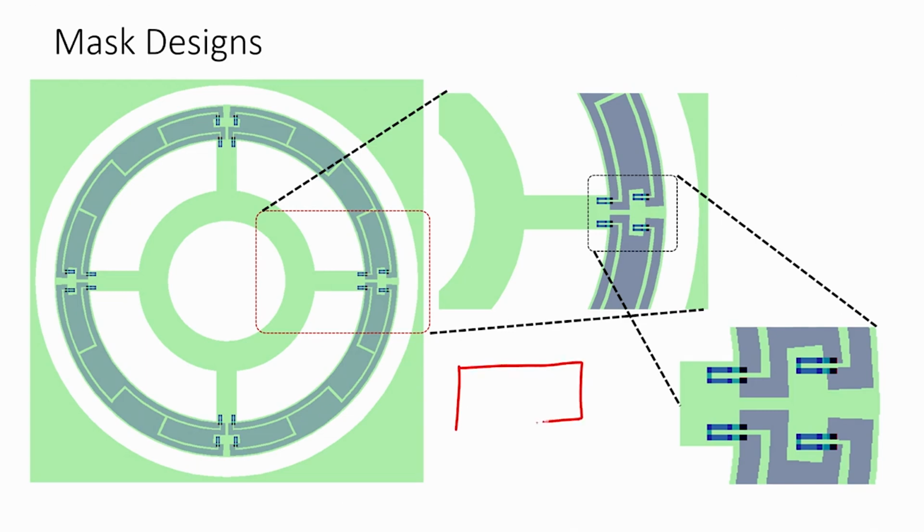If you have an oxidized silicon wafer, alright, oxidized silicon wafer, then let us say this is N type and this is my silicon dioxide, right. What I will do is I will open a window, I am just showing you quickly, okay, so that you understand. I will open a window like this in silicon dioxide, and then I will spin coat my boron. Either spin coat, there are different ways of diffusing boron or impurities into a silicon wafer.